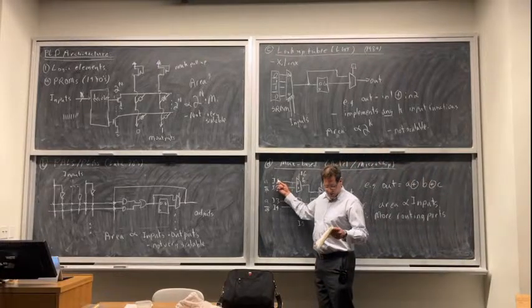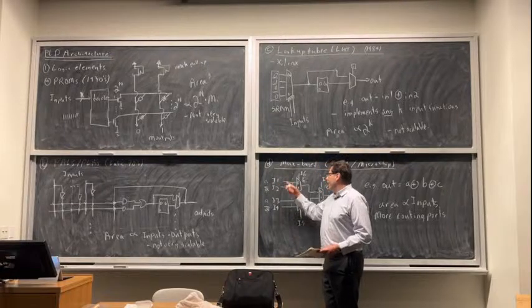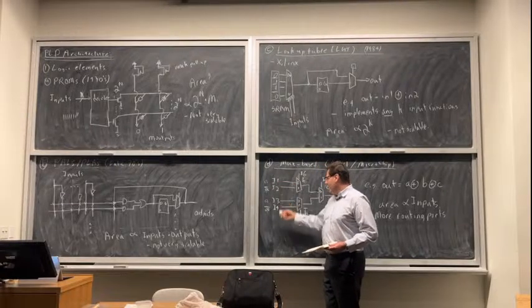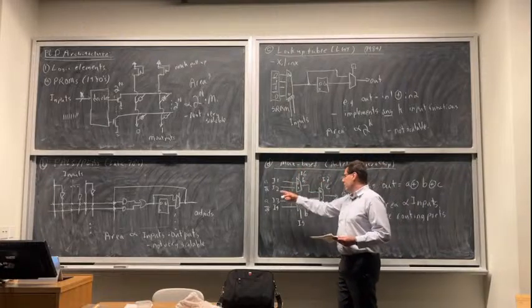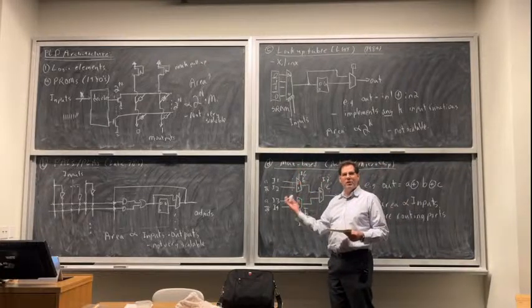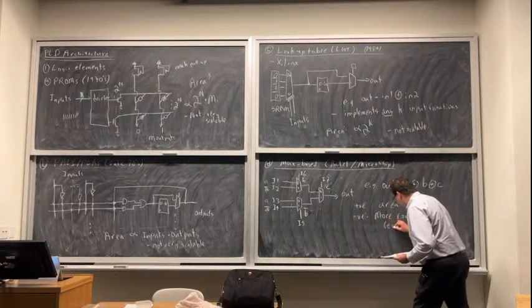And we'll figure out some bounds on that. But yeah, the expense is the fact that we have more inputs. In order to make use of the extra power of this mux, we need to allow more different ways to hook up the inputs, and that's actually a big deal. So more routing ports, which is expensive.